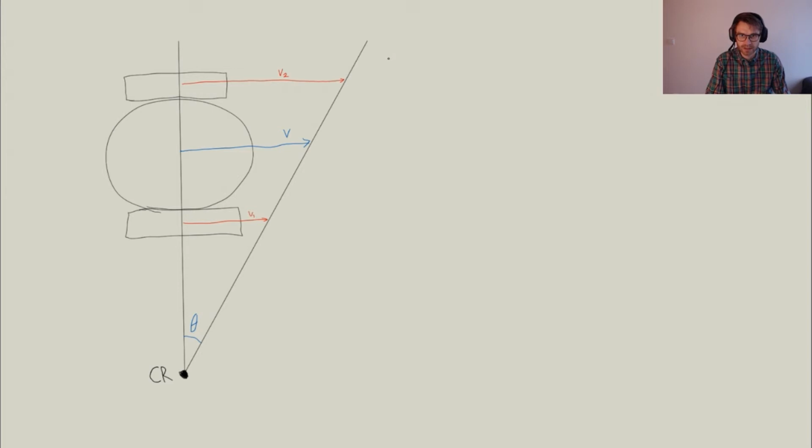The velocity, as I already sort of spoiled, is the average of these two wheel speeds. The radius r is the same for both, that's why it can be outside these brackets. And so here we have the linear velocity of the Turtlebot. How fast is it moving forward?